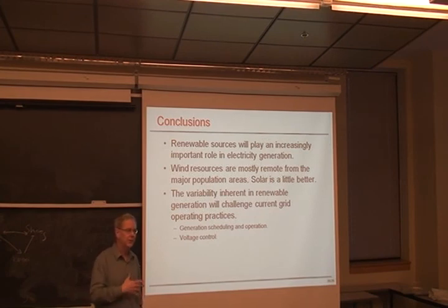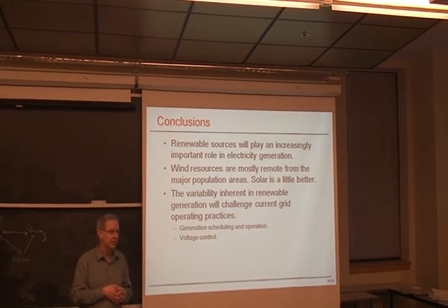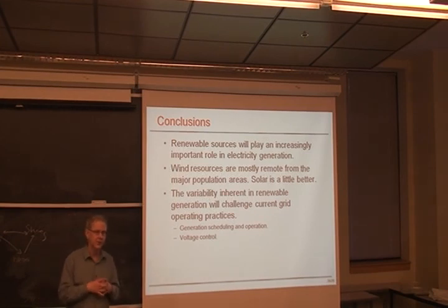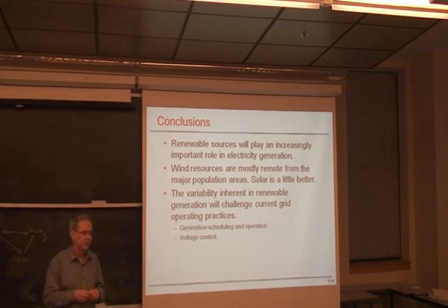If it's combined cycle, it's just about as unresponsive as base load, because you have to be very careful about matching your electricity production with your steam production, which is presumably going off to some other process. So there are operational difficulties with combined cycle as well. Simple cycle is very easy and very responsive, but it's not very efficient and not a good use of resources.